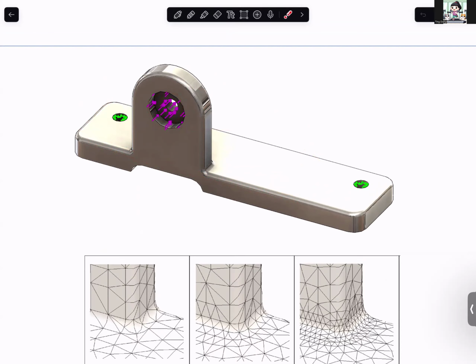And when you do the free body diagram of this part, or do the stress analysis of this part, you separate this component from all the other structure, and here it becomes the force applied by the other component. So you have the boundary condition, you have the force applied, you have the structure, and of course we can do stress analysis. Based on what we learned from mechanics of materials, actually we don't really need FEA analysis here. For this simple situation, we know that this is a bending situation, right?